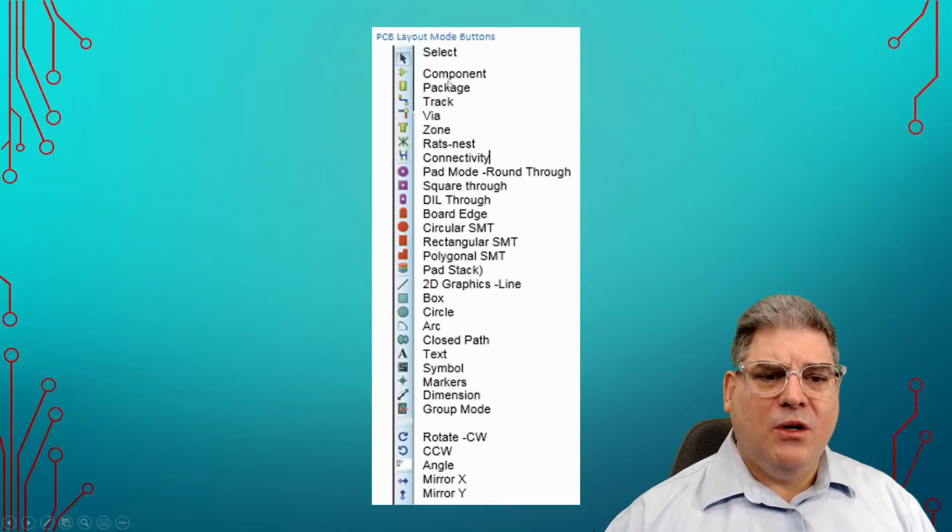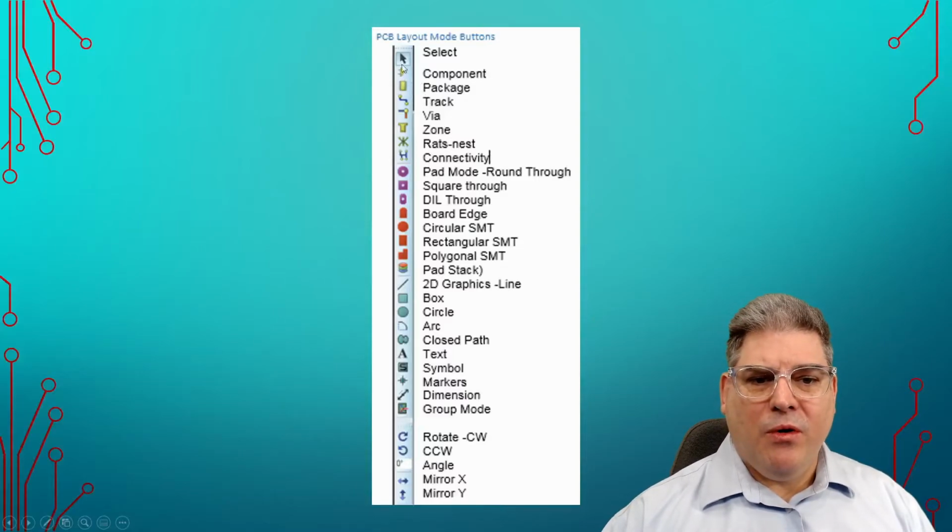Okay, so a couple of them that we will bring to your attention is the selection mode. You're definitely going to be using that. Track modes, you're going to be using that. And note that there is a difference between component and package. If I pick a package and I place it, it'll put just the package. It's not associated with the component.